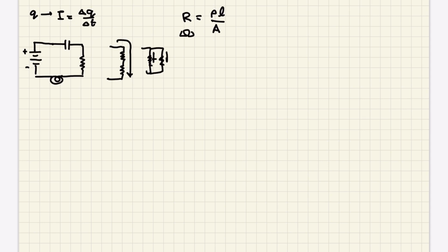That's what Ohm's law is. You can find a relationship between the potential difference, current, and resistance in a circuit that basically says the current is equal to the potential difference over the resistance. And so if you have no resistance, you basically have infinite current, which is basically not possible. So you need some amount of resistance to actually have a current going through it. So this basically says the current is directly proportional to the potential difference, inversely proportional to the resistance.